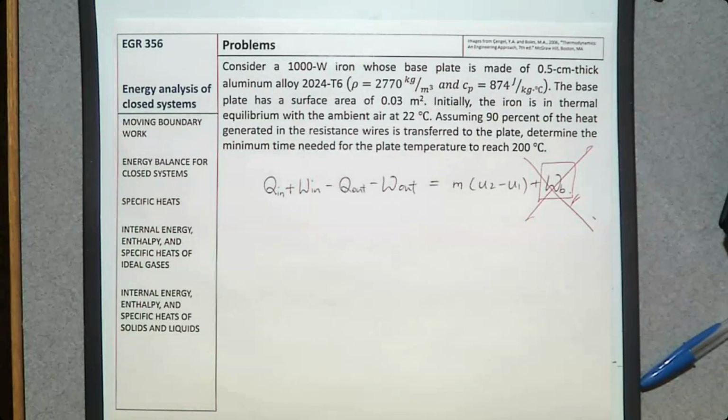But if you install your vent on the floor, hot air comes from the floor, so it is lighter than the air in the room and tries to move up. So it will naturally create airflow in the room, right? That is free flow. But in Texas, they want to cool the room. If they install the vent on the floor, cold air comes in from the floor and sits there because cold air is heavier than the air already in the room.